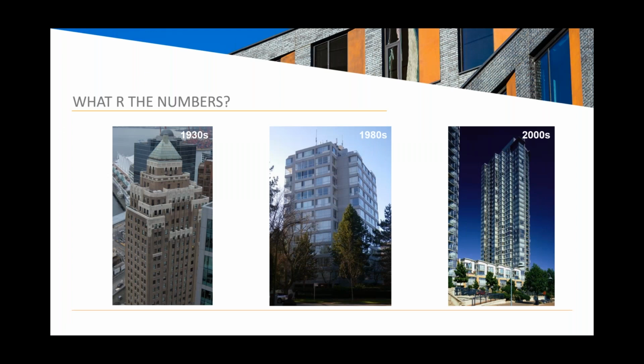So this is a building with much more glass. This building's fenestration system is a double glazed, thermally broken aluminum framed window wall, which includes a slab bypass. That's the portion of the system that covers the structural slab. It has some insulation at that slab, but there are also exposed slabs that you can see on those balcony stacks. And so there are exposed concrete slabs as well. So given that, what are your guesses at the R value of building number 3?